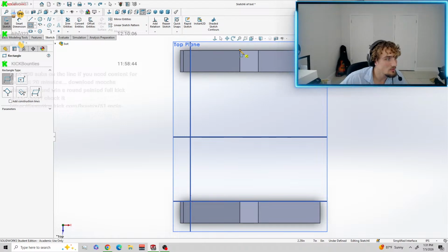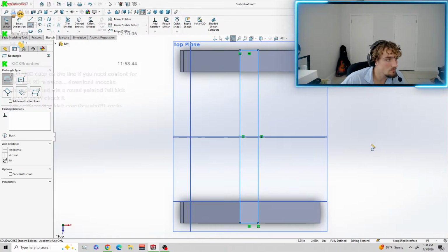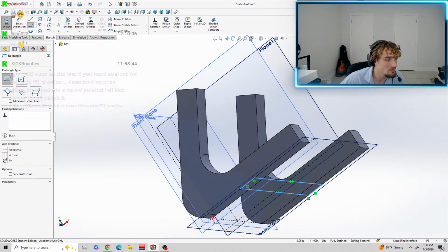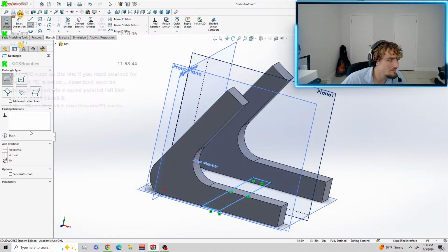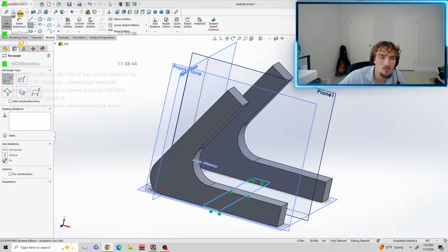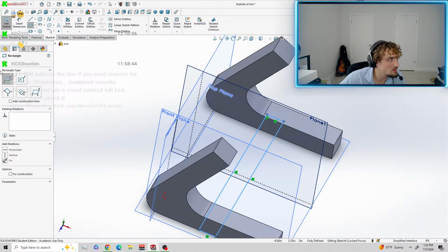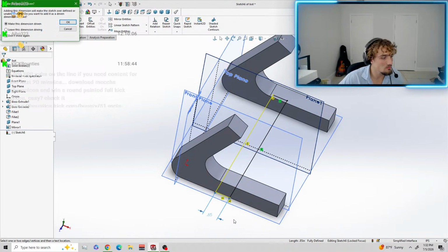And now I want to... Yeah, it's all the way down there, though. Okay. Starting your sketch. Let's see both parts, like the front or top plane. Sketch a profile where you're connecting. Use convert entities on the edges of the two parts if you want the arms to perfectly match their geometry. Convert entities. Okay, so here we'll smart dimensions. 1.